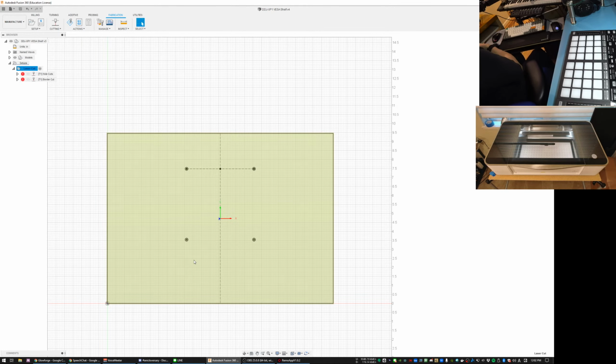So if I were, say, CNC milling, this is where I would specify, okay, I've got a 3-dimensional shape, and what kind of cuts do I want to take to mill out a 3D shape from stock. And this lets you model then things that aren't actually part of your part. You can model the stock, and then you can simulate different kinds of cuts.